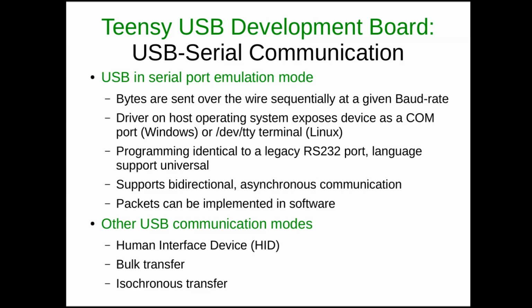Now in USB serial port emulation mode, the driver on the operating system is what actually establishes all this. So when we want to send bytes of information, we just start sending bytes. We don't have to worry about generating that digital signal. The nice thing about USB is that serial port emulation mode is defined by the USB specification. So operating system manufacturers such as Windows or Apple or the whole Linux project, they actually have this driver built in. So in other words, we don't have to install a driver for a USB device if we're using serial port emulation mode, because it'll already be supported by the operating system, which is really convenient.